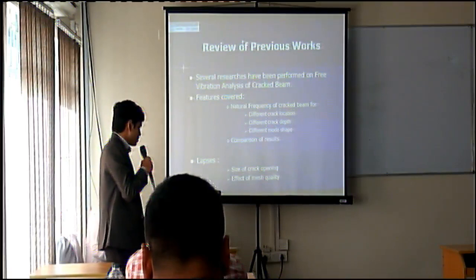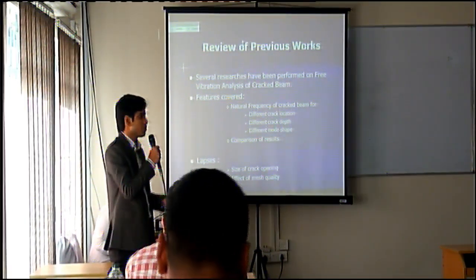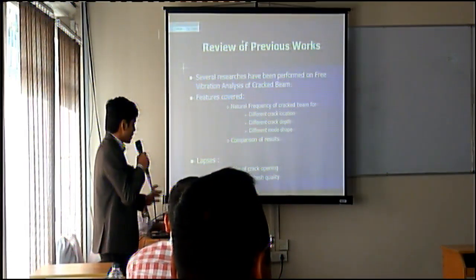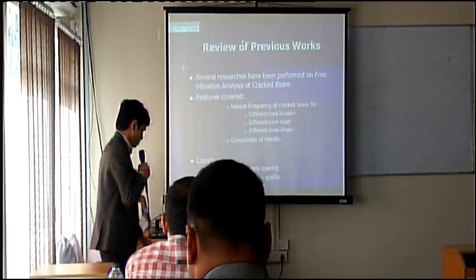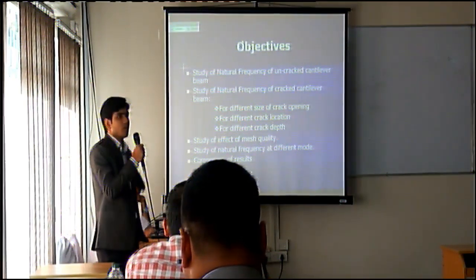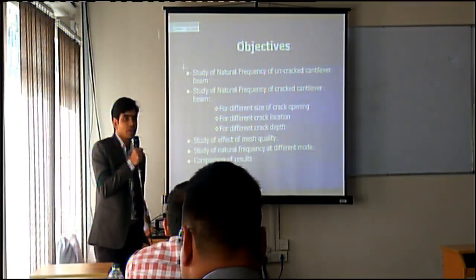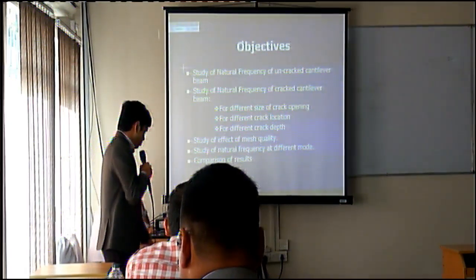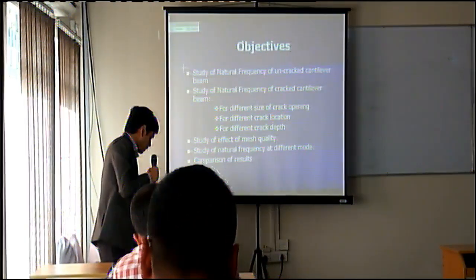So I have taken this topic to clarify my view and to contribute in this field, that how the frequency varies with the size of crack opening or the effect of mesh quality, including all this that have been done already. So my objective is to determine the natural frequency of both uncracked and cracked beam for different size of crack opening, crack location, and crack depth, and also for the effect of mesh quality for different mode shape and the comparison of result with uncracked beam.